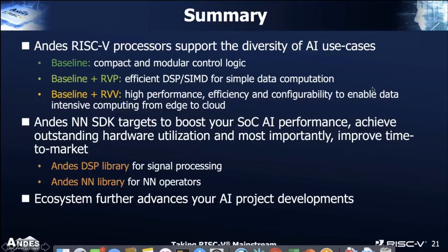Moving on to the DSP capable processor with the RVP extension, we run different code, since the CPU is targeted for different things. For a filter, let's say you're doing a FIR filter, for that same 1 watt of power, we could do about 106, 107 giga operations. So power efficiency is twice as high.